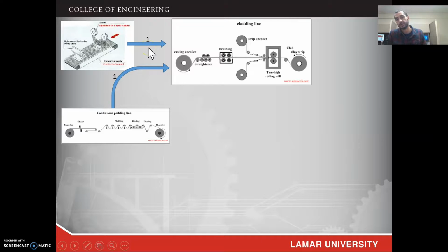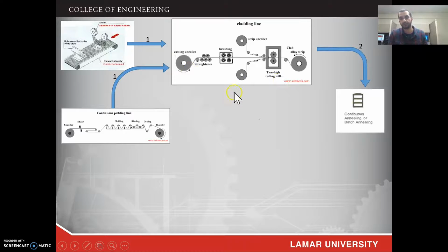In the bonding, a layer of steel will be sandwiched by 2 layers of copper. And when the process is done, we'll go to the next process, which is annealing. In annealing, our product will be heated and it will help it to actually strengthen our alloy.